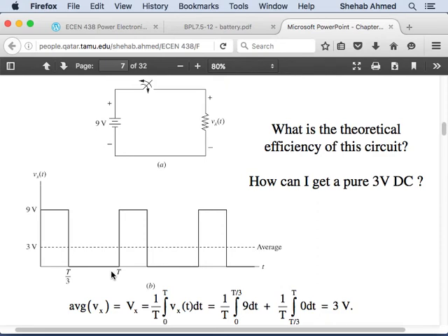So filters are a big deal in power electronics, right? Because they are the workhorse of the power electronics industry. Because you need filters anytime you use power electronics. Because what power electronics does is chop the waveform. Here is a simple example where I have a 9 volt battery, but you can have an AC waveform, you can have a 3-phase waveform, you can have many types of waveforms. But at the end of the day, what you're doing is chopping up these waveforms of voltages and currents.